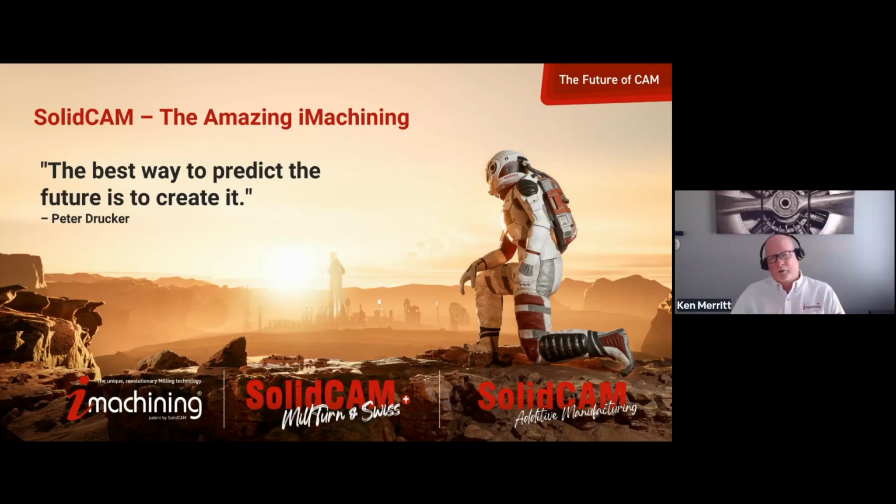The iMachining 3D takes into account the entire shape of the model, especially when we get into complex mold cavity and core type models. It gives us the ability to, in a single toolpath, without even having to pick anything, automatically recognize the entire model, and it does that machining, including scallop calculations, all automatically on that 3D model. Very powerful add-on feature.